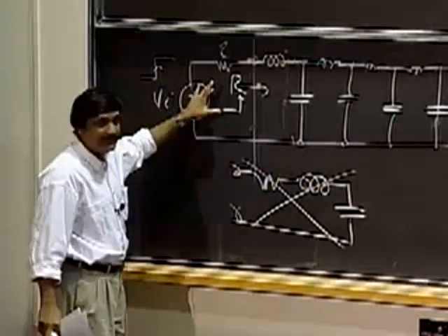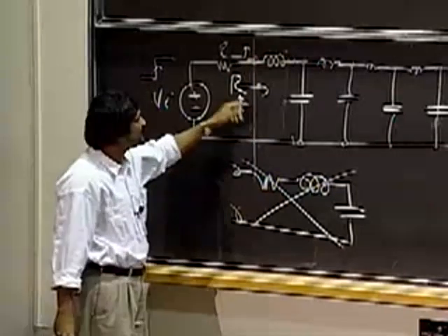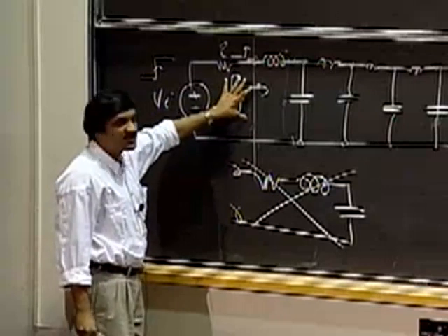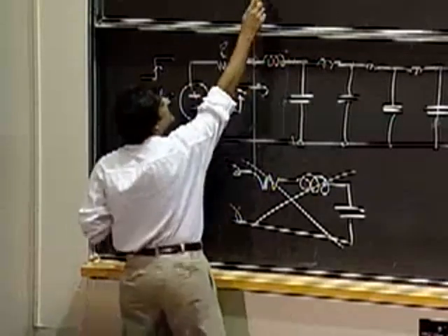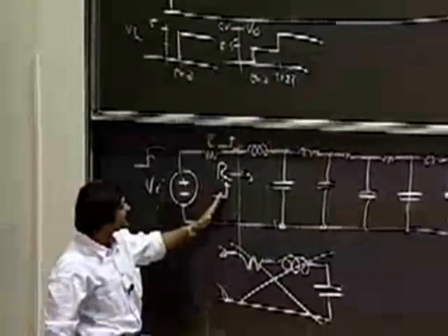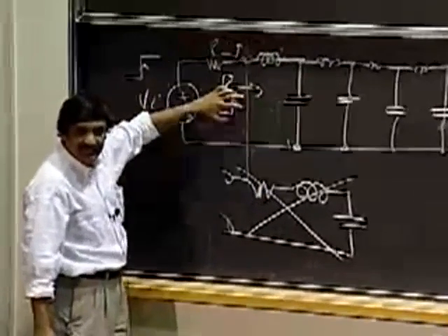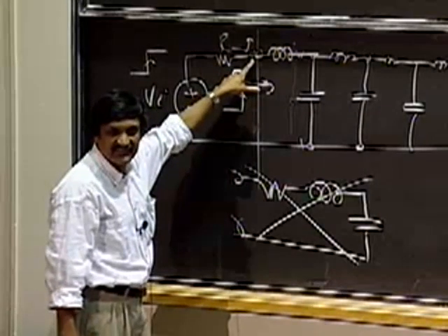So instantaneously, the point at which the pulse appears, looking down here, looks like another resistor to this pulse. Therefore, I start out going up and pausing at 2.5, because instantaneously this looks like a resistance R, a voltage divider, and so it's 2.5 here, instantaneously.